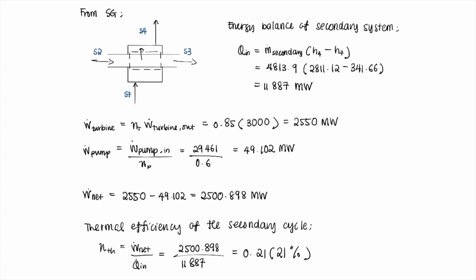This thermal efficiency is quite low because the average thermal efficiency of a nuclear power plant is around 33 to 37%. Due to inaccurate assumptions, there are some considerations that need to be taken, such as common PWRs can withstand about 150 to 160 bar with the operating temperature around 300 degrees Celsius. If the pressure exceeds the limit, there are high chances that the water will boil, therefore reducing the thermal efficiency of the plant. And at a given pressure, the reactor cannot operate at a higher temperature, therefore limiting the overall efficiency of the nuclear power plant.